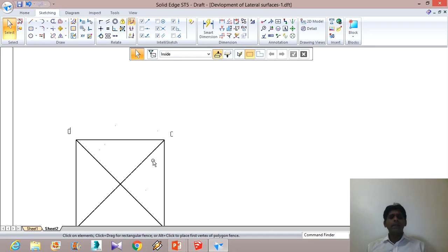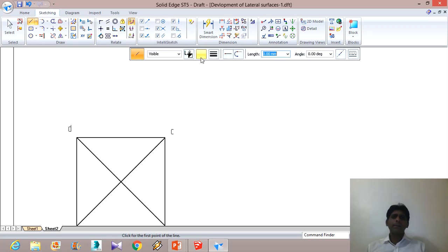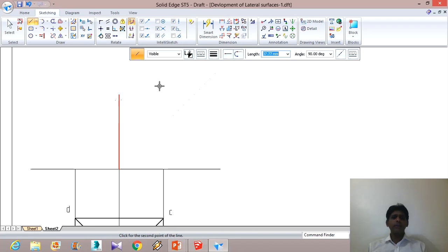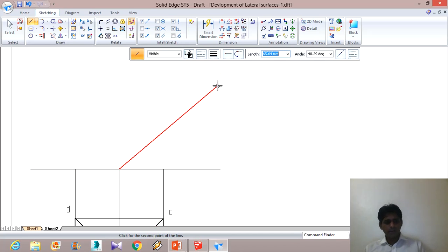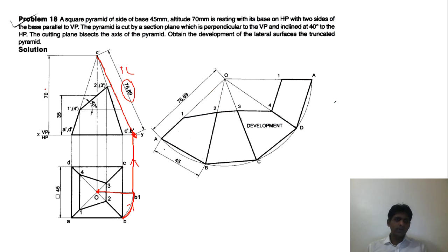Yes. And then next we can go for changing the thickness of the line and taking the projections from this to here, and projections from the end point to this line here, and take the intersection or the midpoint and to this line. This will be the axis. So the length of the axis is 75. If I just check it once, it is 70 mm. It is given here. It is given 70 mm.